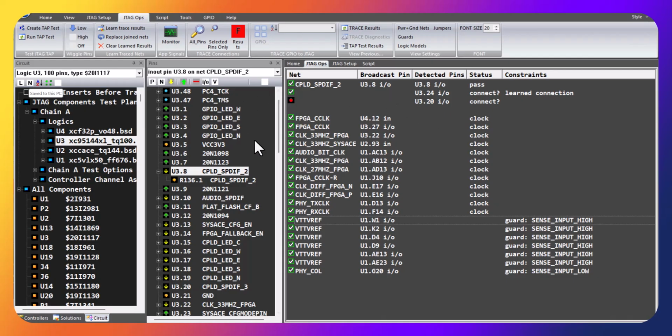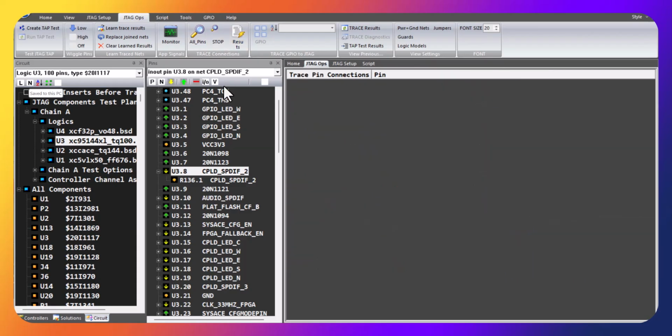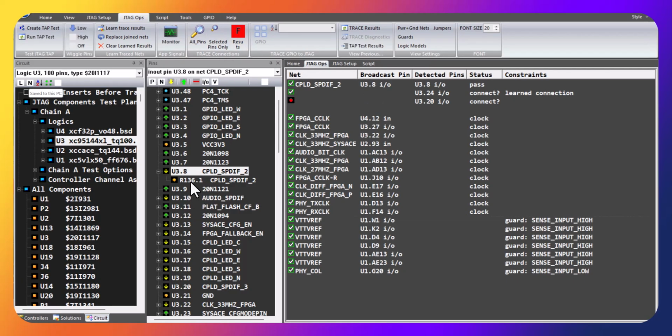And as far as, say, this connection, we just ran a test on this one pin. We'll do it again. We can say, well, why did it show connections to U3 pin 24? So bear in mind, what's happening during these tests, I haven't really mentioned this, is we're broadcasting on every pin. So we just selected this pin this time, but it's broadcasting a signal, and this is where that signal is being detected. So it's showing all your detected pins.